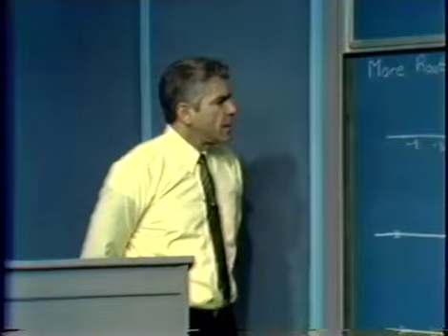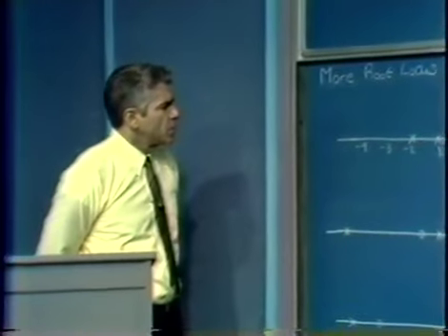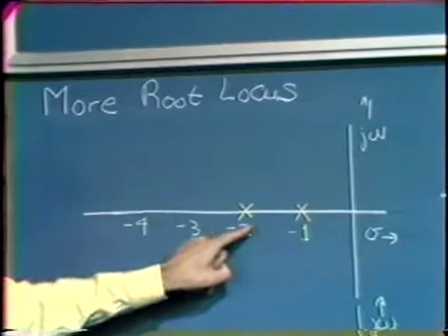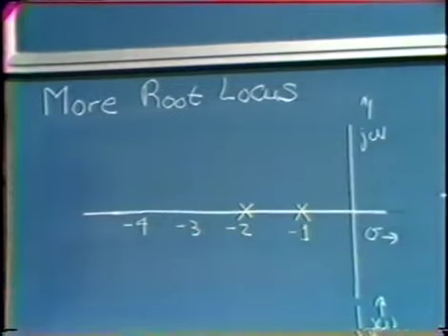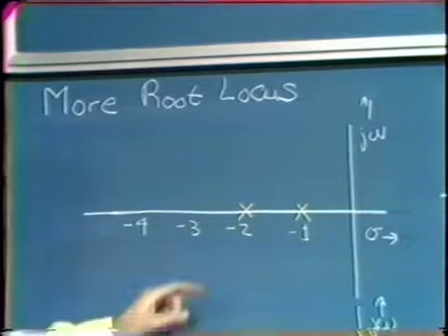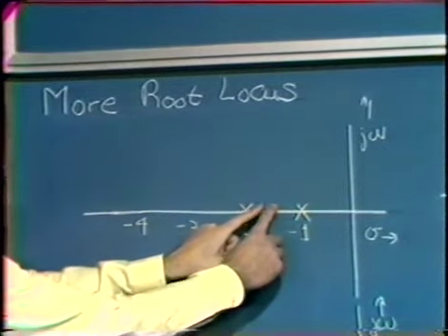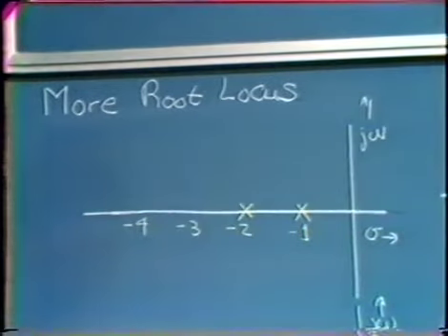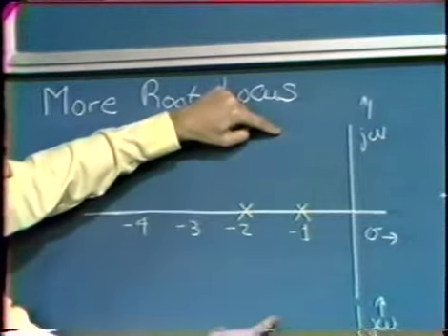Let's start by looking at a second-order system. In other words, assume that we have a loop transmission that has two poles associated with it. We've looked at that configuration before, and recall that if we do a root locus diagram for that system, the two branches come together on the real axis, split off, and then further increases in A0, F0 result in a progressively smaller value for the damping ratio associated with the resultant closed-loop complex conjugate pole pair.